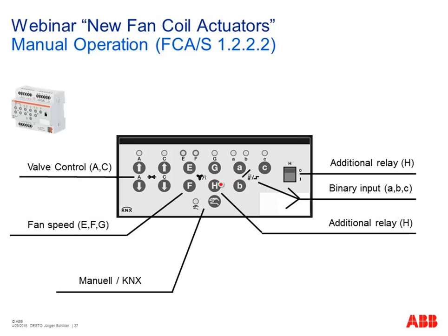Plus H is the additional relay output. You can operate it via the button, but as it is also available in direct mode, you can also use your screwdriver and operate the lever of the relay mechanically. So, standard way of manual operation.